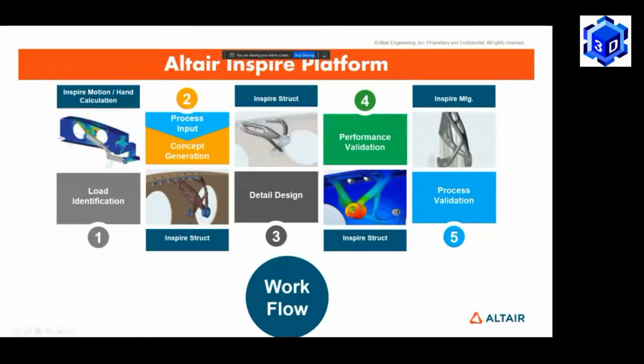If it is a geometry reconstruction related issue, then you can go to step number 3. If it is more fundamental, such as a design creation related issue, then you can go to step number 2. And if it is even more fundamental, you question the loads applied itself. So, for example, you assume that the human jaw will take 10 kilonewton load, but actually it should take 20 kilonewton load. Then you have to go to step number 1 itself and start those loops.